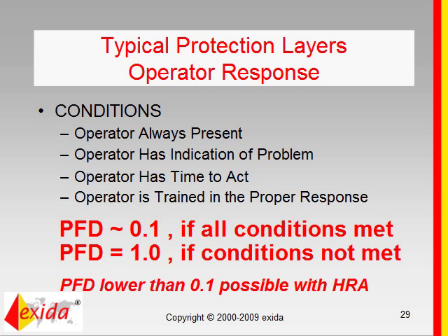One question here: how can you claim less than 0.1 for the use of a safety PLC if the I/O is not rated? In my statement of claiming less than 0.1 for a safety function, I should say safety function versus a control function, and my assumption there was that the entire loop was a safety instrumented function. So it's not just the controller itself. I may have hinted that I was talking about the controller itself. I talked about an entire safety instrumented function versus a control function.